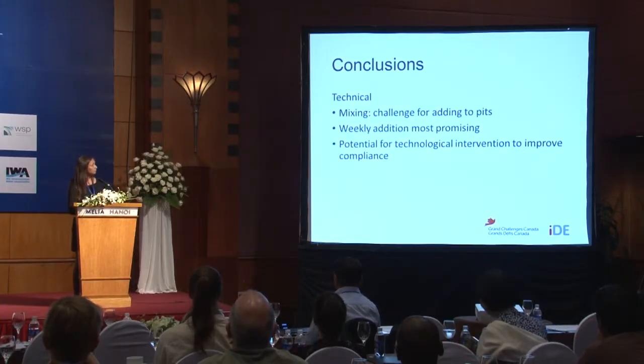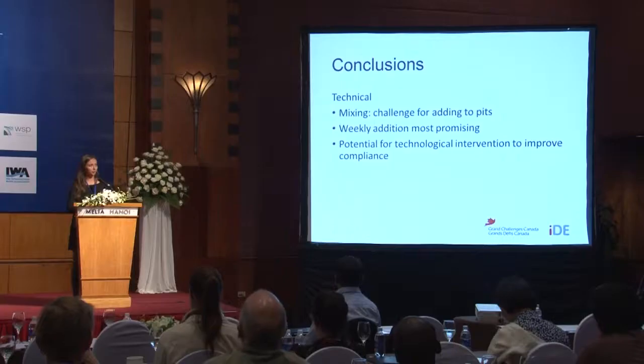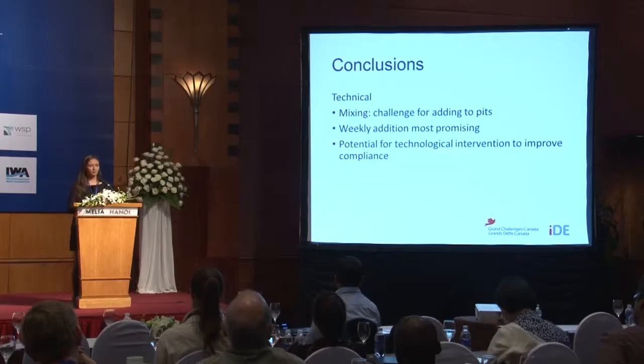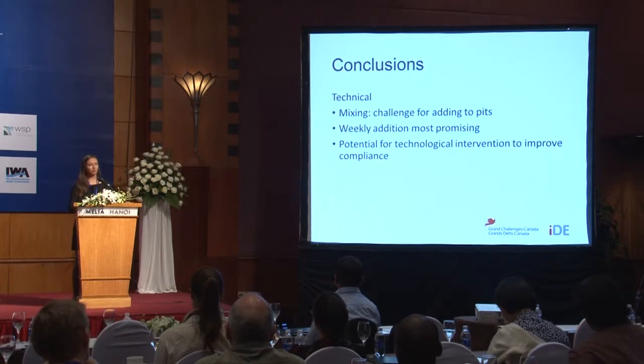So some conclusions on the technical scale: mixing is a big challenge for adding lime directly to the pits. And on a user basis, the weekly addition seems the most promising. There is also potential for technological intervention to improve compliance. So one of the ideas we're considering now is maybe designing some sort of flushing mechanism, so the lime is added when you flush the toilet.